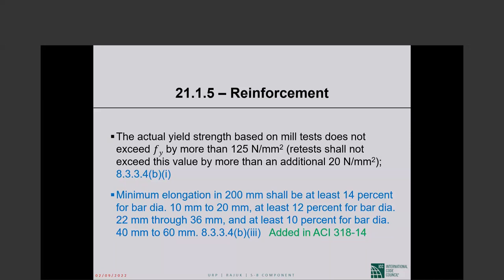Okay. So once again, if the yield strength is higher than you specify, the moment strength of your member will be higher than you bargained for. That high strength member will attract more shear force to itself in an earthquake. Shear and moment are related, remember that.